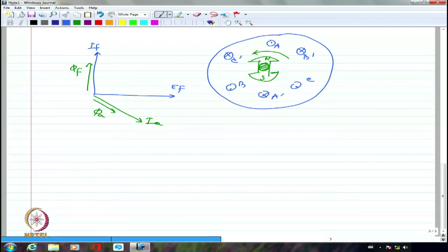What we are doing is, the DC current, although it is injected into the rotor, you are physically rotating it. So the DC current is not producing a revolving flux. You are physically rotating it to create a revolving flux. So you can look at the DC current as an equivalent per phase AC current in a three-phase system. So there is an equivalence we have to calculate, definitely. So rather than mentioning this as IF, let me mention this as IF dash.